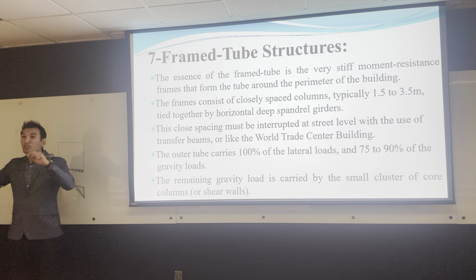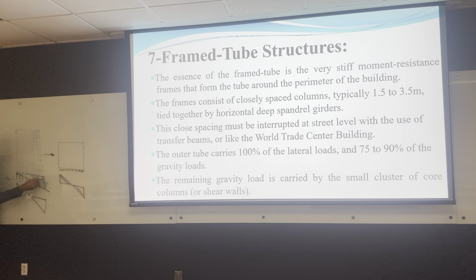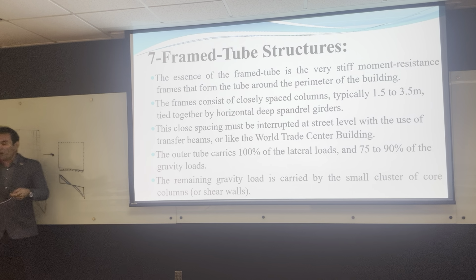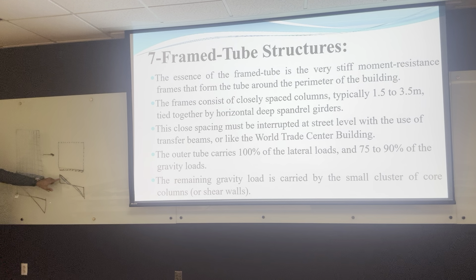But if the beam connecting these columns is very stiff, like the story height, like if this beam depth is, let's say, 1 meter, it's good. If it's 2 meters, it's much better. What if it's the story height? That's actually a shear wall, right? So this beam is gonna move as one piece. But if it's not stiff enough, it's gonna have a little bit of deflection. So that's actually what happened. It pulled this column, so you are losing this.